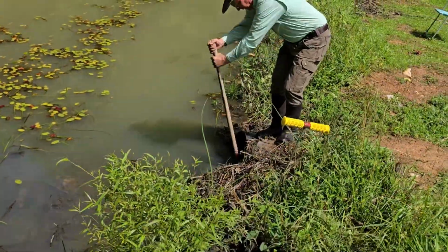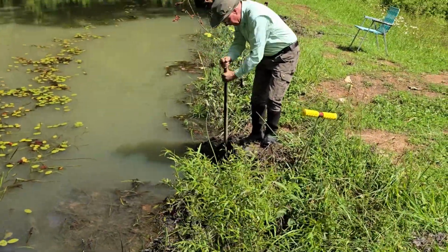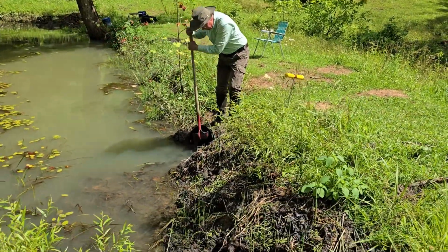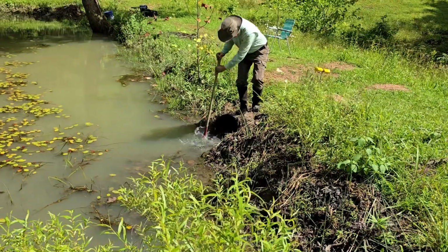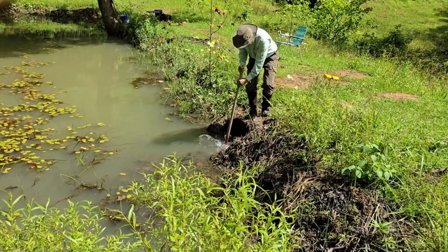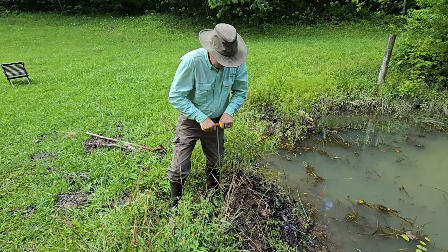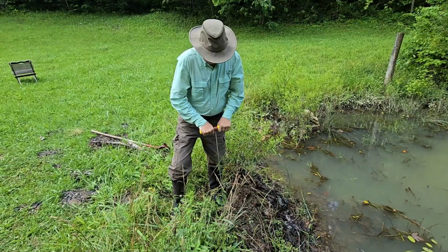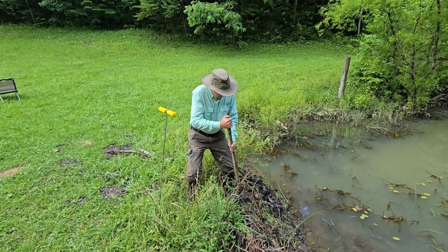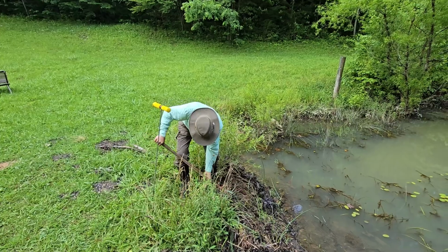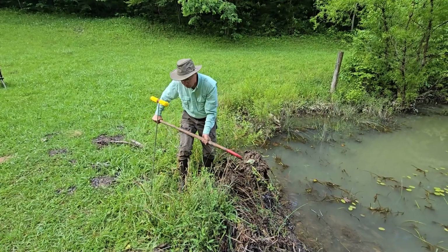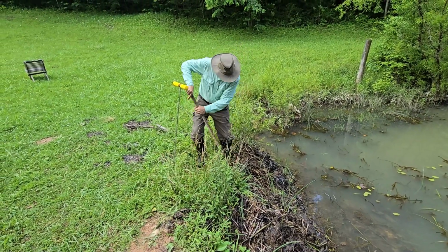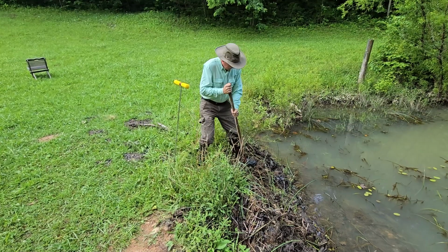I used a shovel to remove the soil and plants that were partially blocking the entrance to the large diameter buried pipe. The beaver had built a low dam using mud and water shield that was found growing in the pond. I then used the tile probe to find the exact location of the entrance to the overflow pipe that was completely blocked by beaver. Using a shovel, I removed the beaver dam that was completely blocking the entrance to the smaller diameter overflow pipe. It's very important to keep these pipes open, as one heavy rain can cause enough water to flow over the dam and wash out the dam.